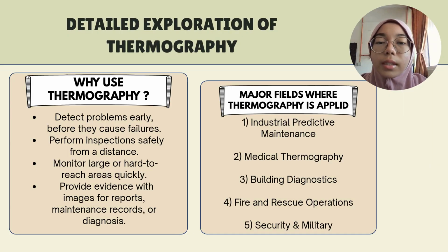Let's move on to the detailed exploration of thermography. But before that, we must know why industries nowadays choose and use thermography in their instrumentation applications. The first one is that thermography can detect problems early before they cause failures. Other than that, thermography can also perform inspection safely from a distance. It can also monitor large or hard-to-reach areas quickly, and it provides evidence with images for reports,